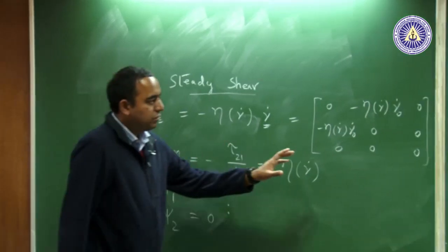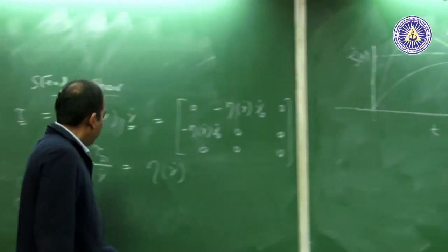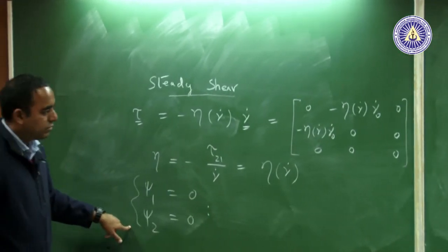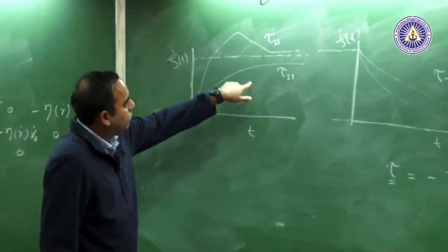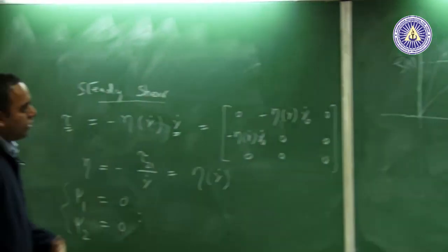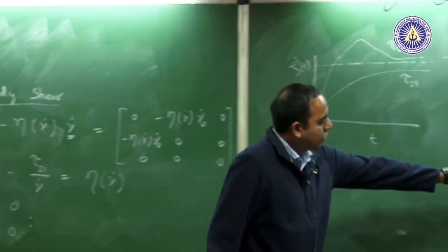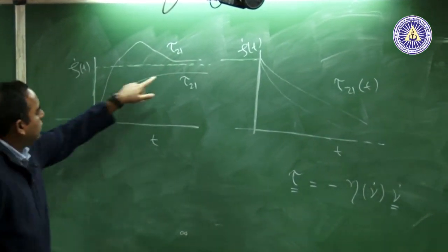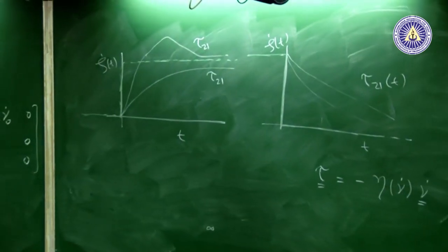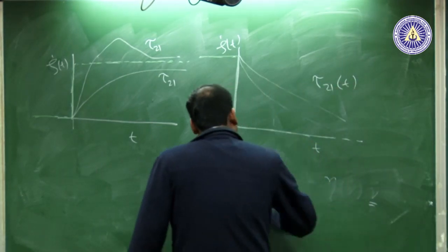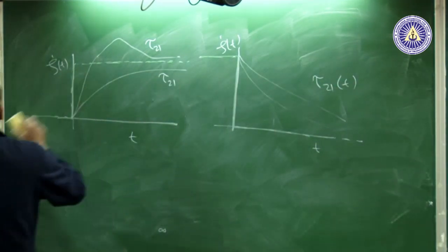So, in terms of modeling, what we have achieved so far, after introducing the GNF class of fluids, is that we can capture the data more nicely for steady shear. We cannot capture elastic effects though, and we keep failing miserably in these sorts of experiments where the shear rate is transient. Because of its similarity to the Newtonian model, it will just follow the shear rate instead of showing all these beautiful curves that come up from experiments. So, then it poses the next question: what can I do to address these curves?